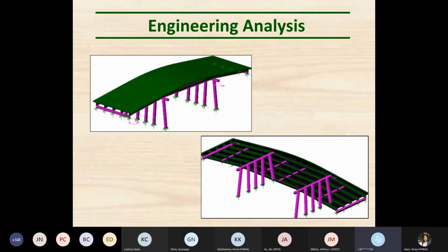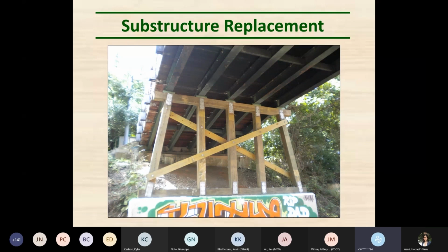And the general conclusion they came to, I believe, was there were some limiting factors in the steel stringers, which were quite small on the approach spans, and then the cap beam on the timber frames was a controlling factor as well, especially with the level of deterioration that we reported. So next slide. So they made a decision to replace it. Here's a picture of the new Southern Pine treated frame bent installed. But because they made their decision, that gave us an opportunity.